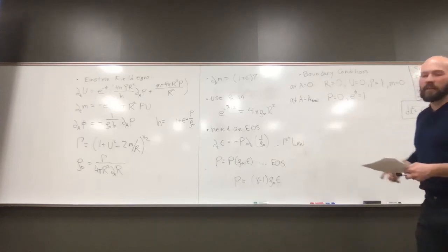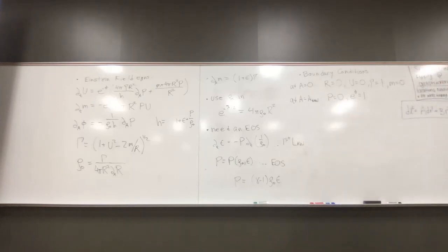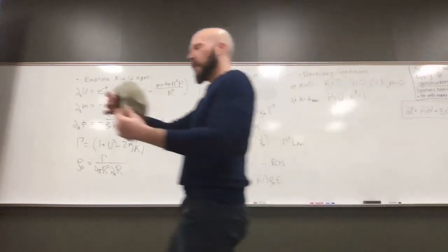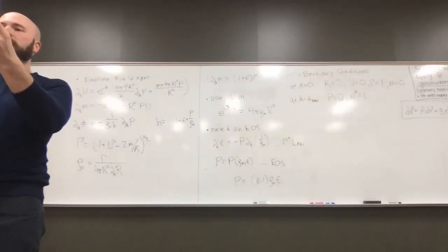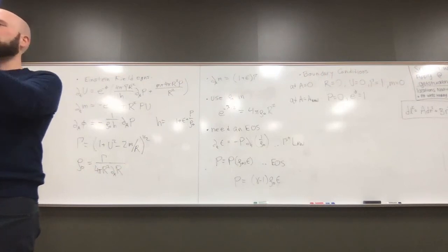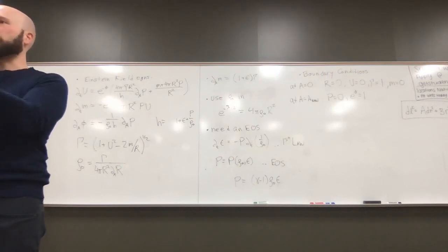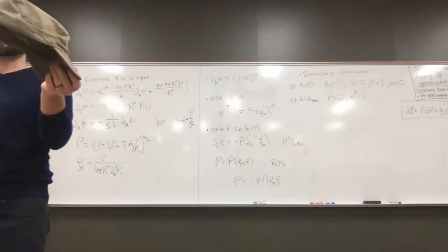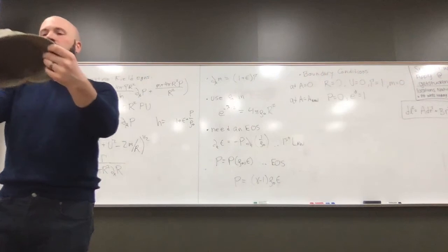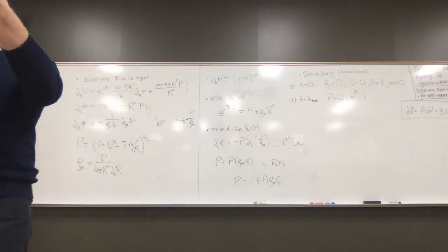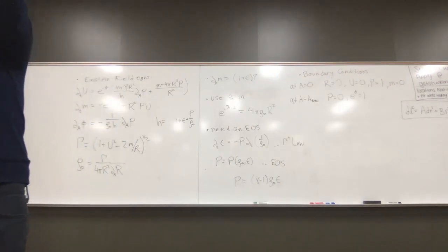The reason being, in Lagrangian grid-based codes, okay, so I've got some fluid element, right? This is my fluid element. And I can shift and shape this thing, and its mass doesn't change, right? But its spatial shape does, its volume does, everything about it does. What can happen in a grid-based multi-D Lagrangian code is that you can get shear of a mass element to go like that.